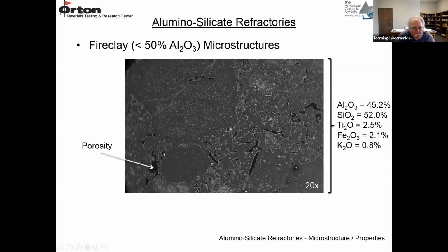You can see in this micrograph some outlines of some coarser aggregates. This is the pre-fired portion. You can see them, and then in between is the raw clay that's been sintered. Everything has the same chemistry, whether it's the matrix or the coarser grains. But basically, you have coarse pre-fired grains surrounded by a matrix of the raw clay that's now fired.